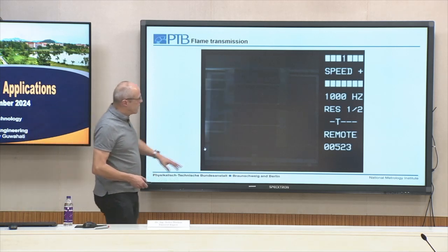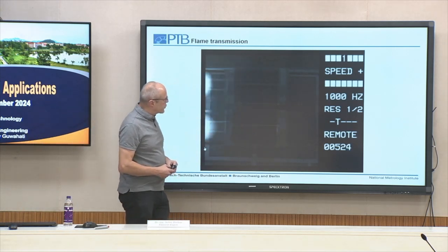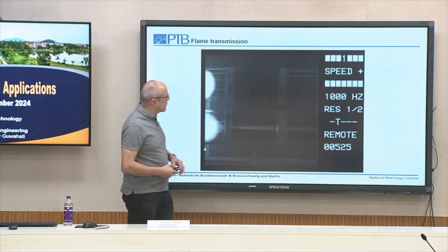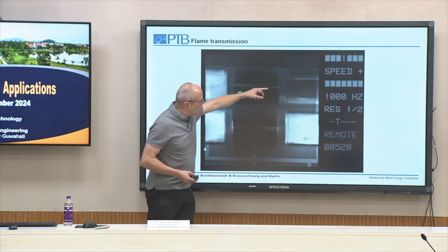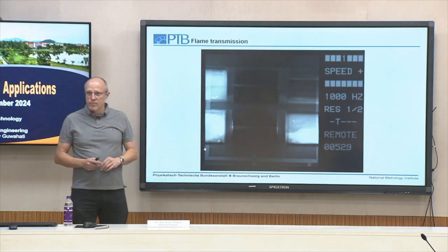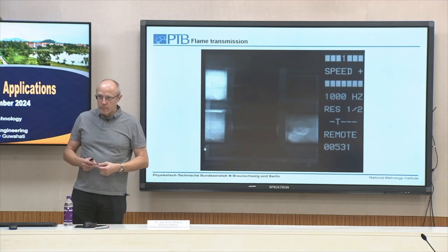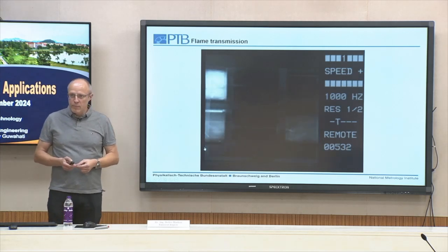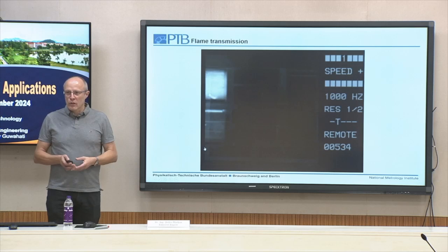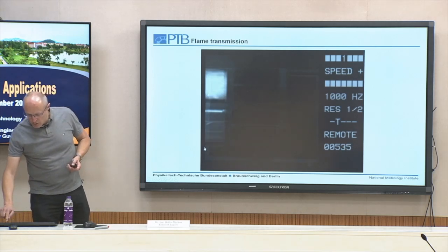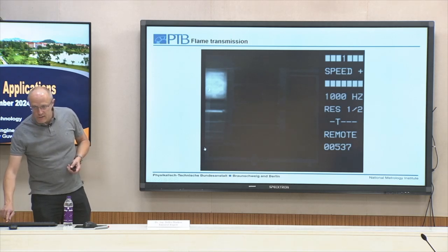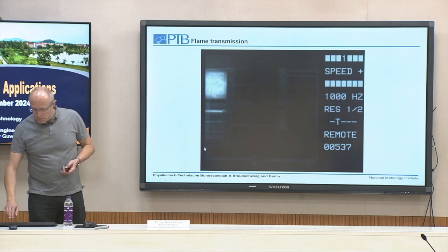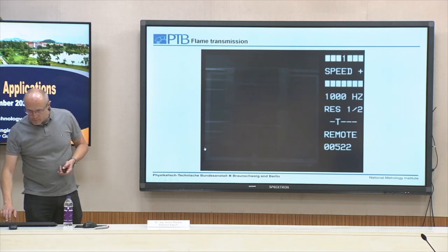But what you also see is, if we have the slightly larger tube here, there is a flame transmission. In case of the smaller tube, we see here some chemiluminescence, but the flame is finally quenched in the system, and so no flame transmission occurs. We will discuss tomorrow in more detail the effects and reasons why we can see flame quenching using, for example, flame arresters.